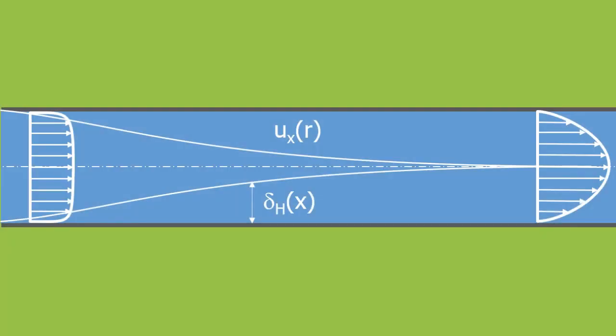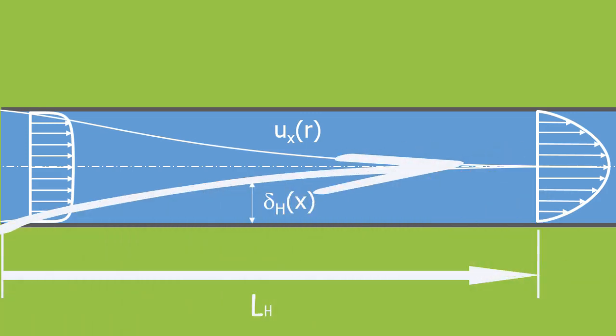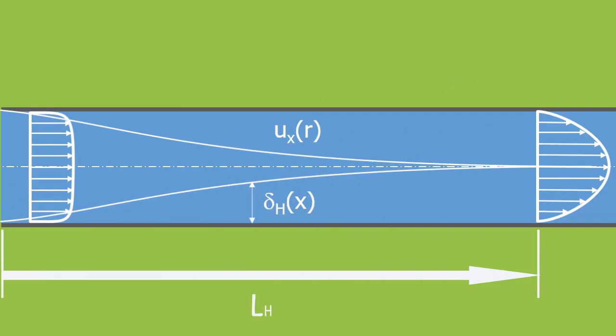In the circulation inside ducts, a very important aspect is the entry effect. When the fluid enters the duct, it takes a certain distance for the velocity profiles to stabilize. At the entrance, the boundary layer is very thin. It grows until it covers the entire duct cross-section and reaches a stabilized profile.